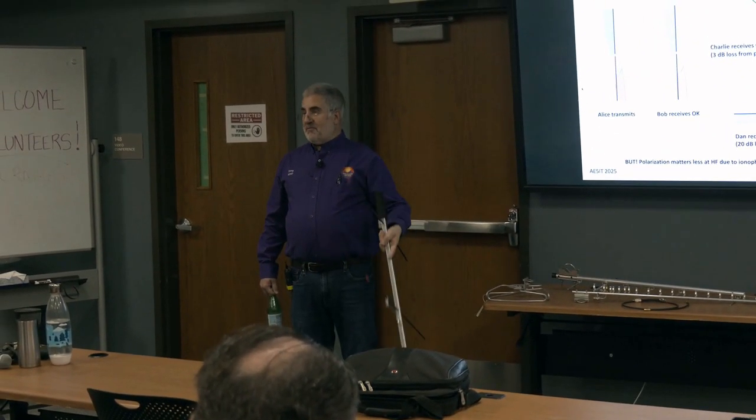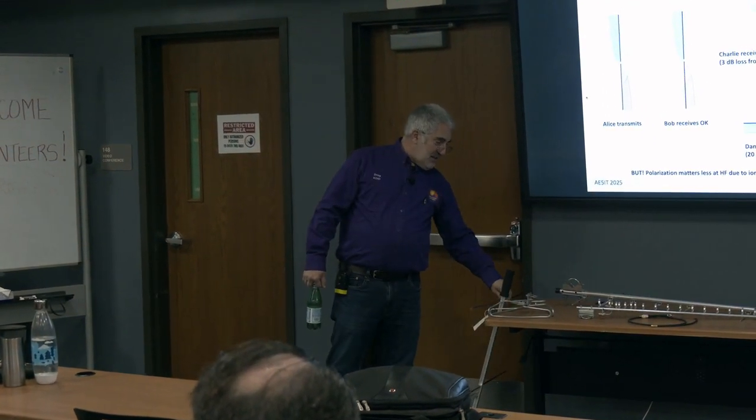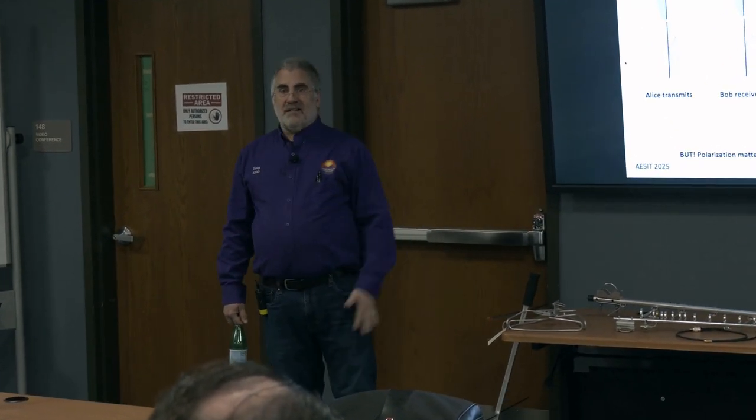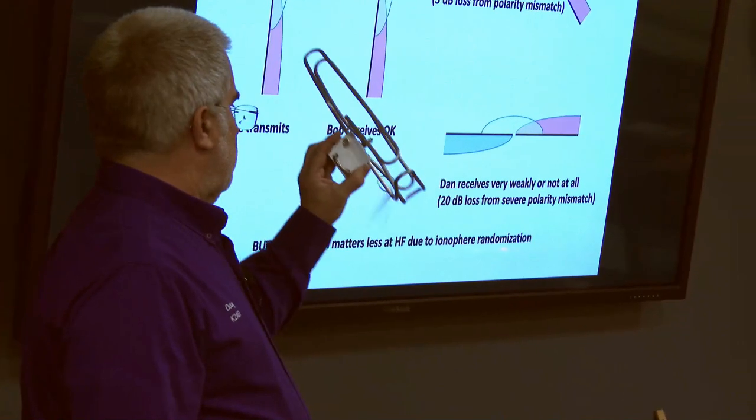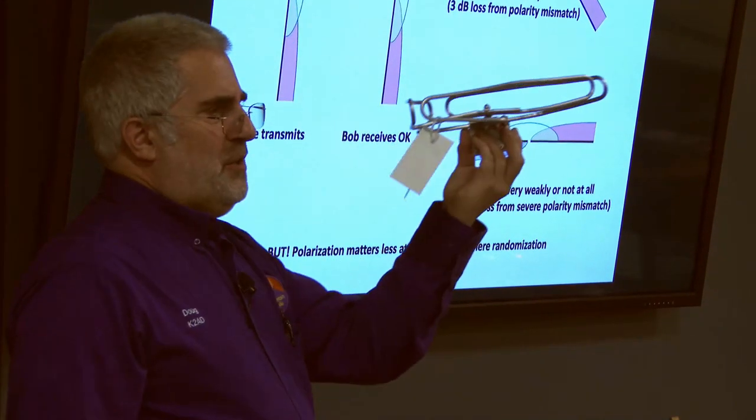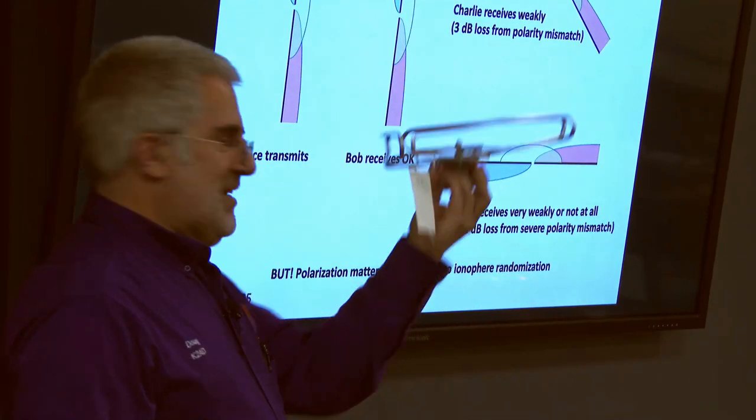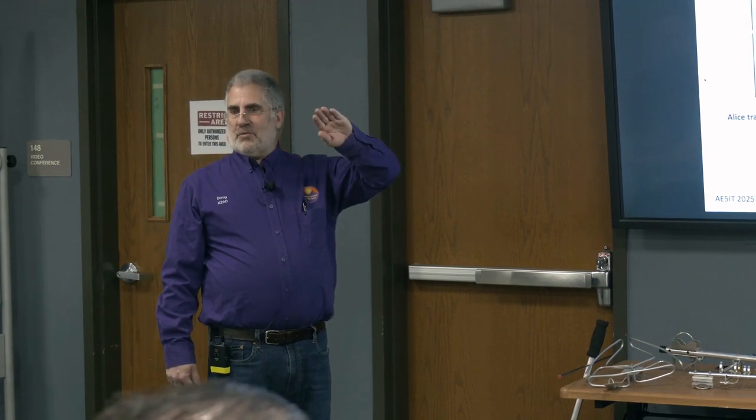No, so we run a vertical, so hence why these things in practice tend to be vertical versus horizontal. Somebody brought this nice little, I call this a clover leaf, but this is a horizontal omnidirectional antenna for 400 megahertz. Who brought this? Chris, great little antenna. But we don't want to run around with this on our car when we're trying to get to the local repeater. So kind of the difference between why these are.